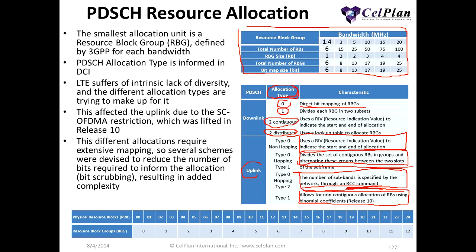So we can see clearly here that the decision of using SC-FDMA was really a little bit problematic, and that not using permutation was even worse. So they are trying to compensate this with the new releases and trying to add diversity, and also the decision to use reuse 1, they are trying to compensate this in the control channel by providing more repetition and so on.